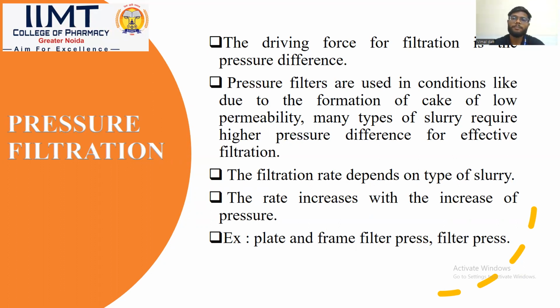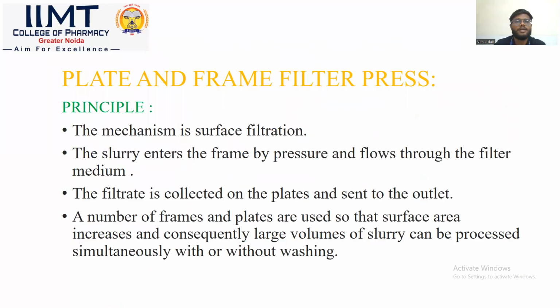So, if we apply a pressure in the normal filtration process, it will speed up the rate of filtration. So this process is known as pressure filtration. The filtration rate depends on the type of slurry. The rate increases with the increase of pressure. As we increase the pressure, it will directly increase the rate of filtration. Example, plate and frame filter press and filter press.